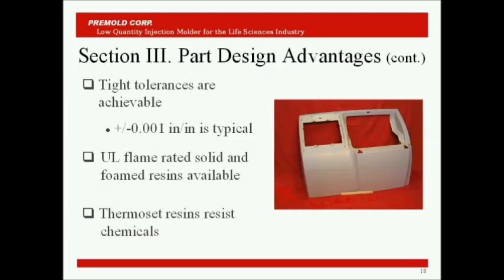You're dealing with low pressure and low temperature flow, and a chemical reaction to form the solid plastic part, relatively stress-free. RIM parts normally have tolerances of thousandths of an inch per inch. The tolerances are normally stated on an inch per inch basis because it's not unusual to be dealing with large parts with the RIM process.